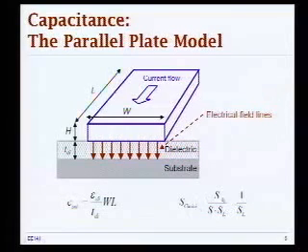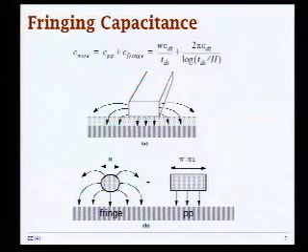And then we went into scaling a little bit and discussed several scenarios where you have long wires, short wires, and so on, and you can derive expressions for various scenarios for wire scaling. And we said, well, this is a really simple model that is not really applicable to practice, but it's good to start from. There are other components that we need to worry about, especially since the scaling of wires has adopted a trend where not all the vertical and horizontal dimensions scale by the same factor, but rather the height of the wire stays about the same.